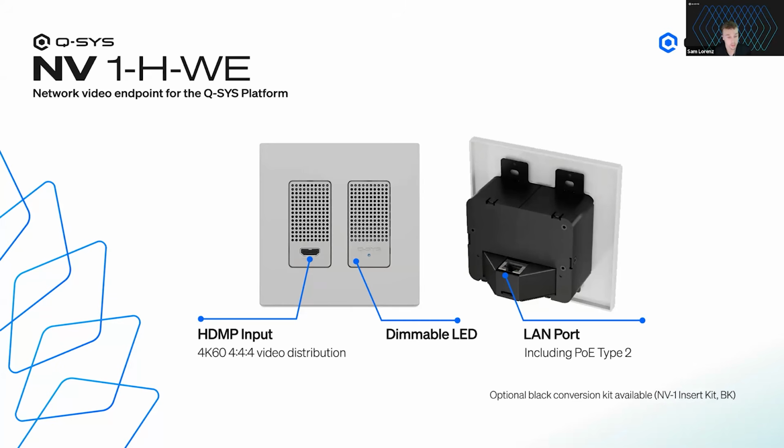You do have a dimmable LED, so that LED you're able to route or control however you want within the Q-SYS world. So if you want the LED to turn on when there's a valid source signal on that HDMI, you're able to do that. And then if someone unplugs that, the LED then dims back down.